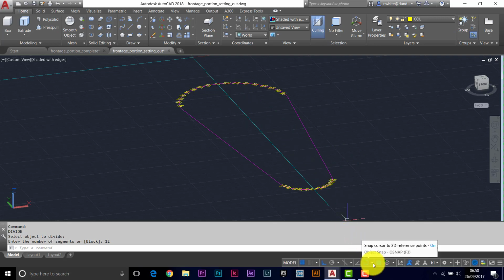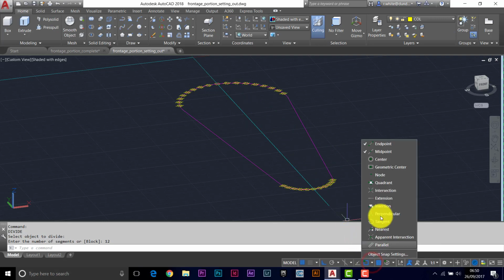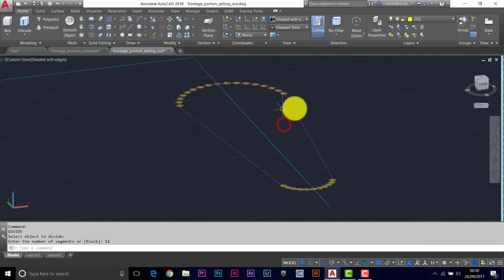Okay, we'll check our object snaps now, because we need node as well. Okay, midpoint, not going to be used. Okay, so we'll take that away. So we'll just have endpoint and node. Okay, and now we trace around this carefully with a polyline. So PL, enter. Remember there's a point to pick at the end of the line before the curve starts.